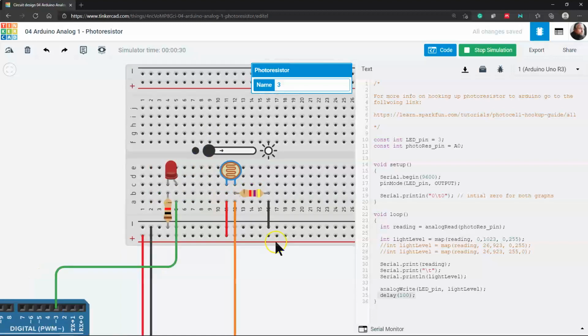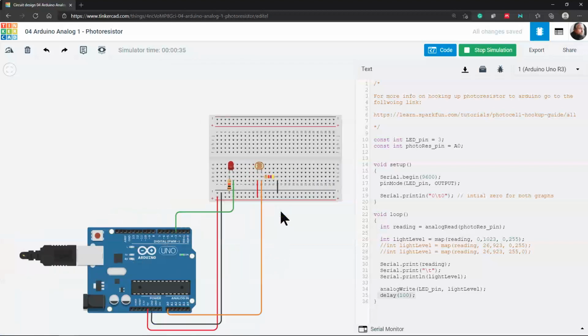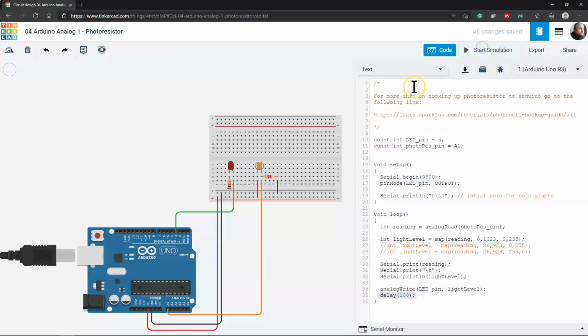So going up, going down. So the important one that makes this different than the previous circuit where it's hooked up to the actual 9-volt battery is that it's what's coming in here for these values, and we decide in our code what's going to happen and then sending it out. So we have our sensor, we have our controller physically here, and we have our actual effector that's changing the outside environment. So that's our body of the robot so far, and what it's doing for its sense, think, act, reading the value, thinking and changing the value and outputting some stuff, and then coming back here. Okay. Now let's stop the simulation.